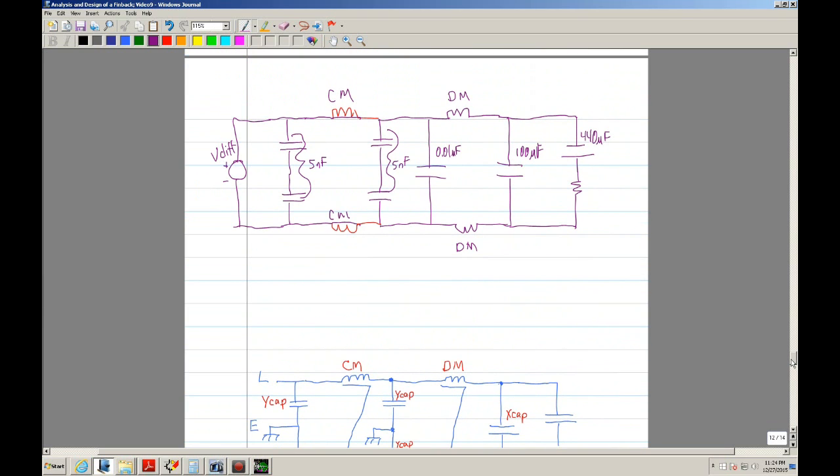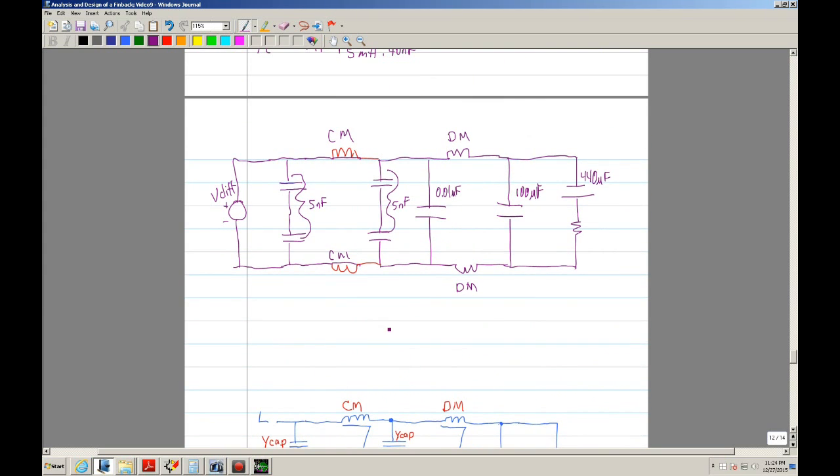So now what you can do is calculate what the corner frequency is going to be. It's going to be 2 pi. In this case, this is, I believe, 15 microhenry, so it would be the sum of both, 15 microhenry, times the total cap. These are in parallel with this and that, but they are so small that they get swamped out.